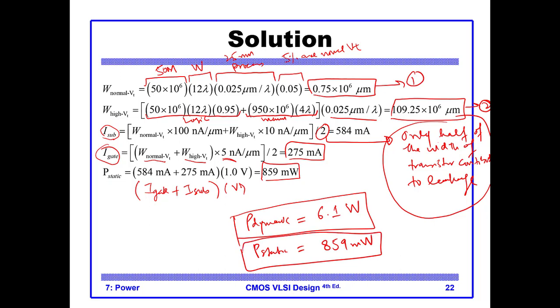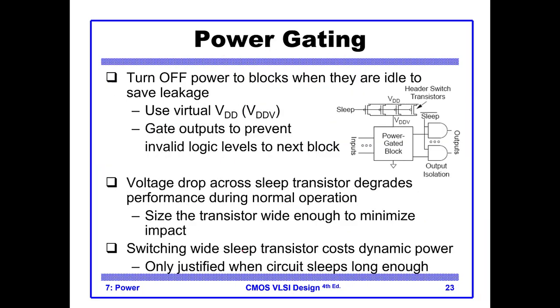But still this is a wastage, because the static power is consumed when your chip is not performing any useful work. So one way to reduce the static power is to use power gating. This is how your laptop works. Remember, in your laptops you have a sleep option.